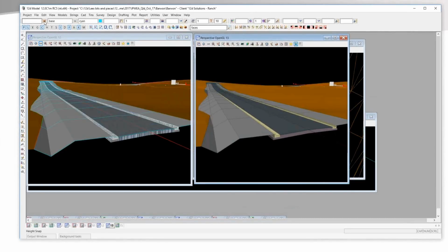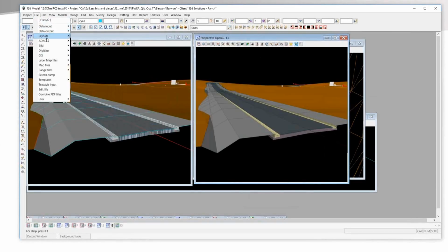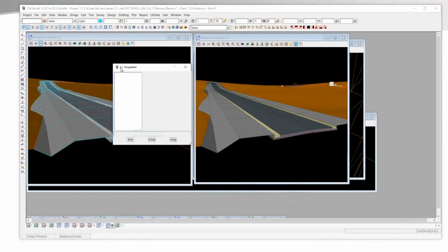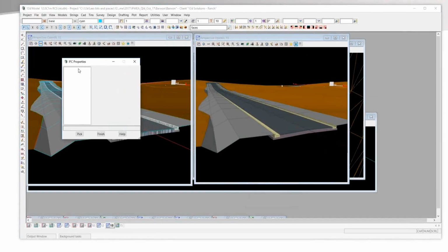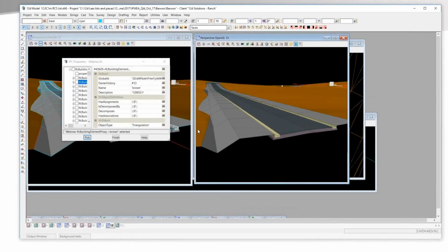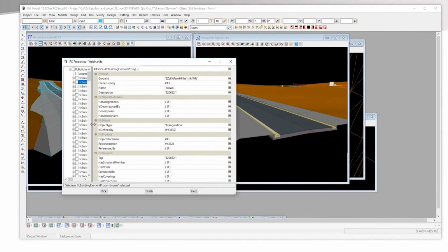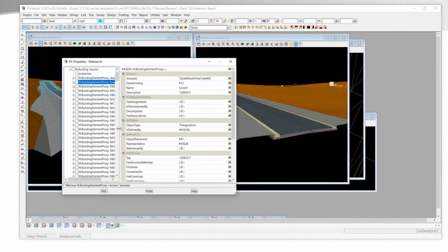Well, before I get rid of it here, I'll just go into, I should have left it out there. There's another one called IFC properties. And what this is, if the IFC file is still here and we pick on something, it actually runs through the file and picks out that information we're discussing that goes with it. So this thing has a global ID, and there's the global ID number, which is so unique in time and space, but I hate to be trying to refer to it very often.